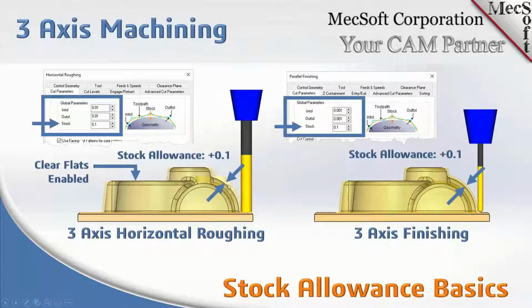If you look at this closely, you see it's got a stair step for the cut levels, and it'll leave the amount of stock from any point on the perimeter bottom edge of the tool away from the part surface. And if you use clear flats, you'll see that it cuts right down on the flat areas. That'll clear that stock from all the flat areas.